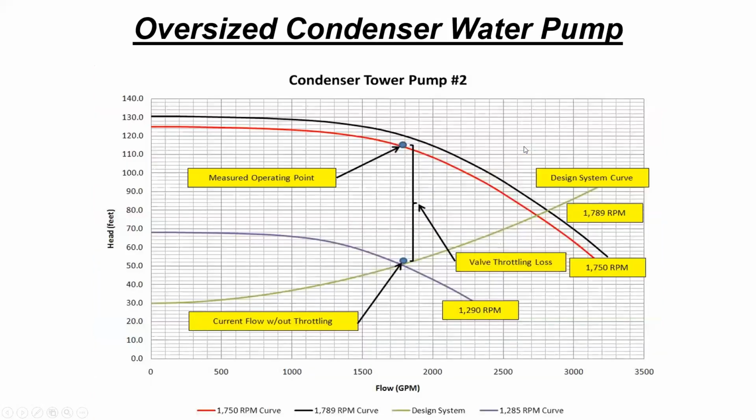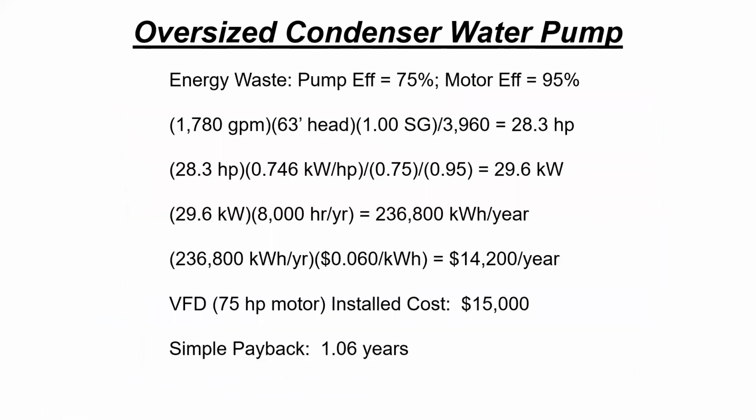So we're talking about going from here to providing this much flow rate, let's say 1700, by opening the valve, reducing the pressure drop by using a VFD and bringing the head down all the way to 50 from 130, let's say, or 120. Again, opening the throttle valve, but using a VFD to bring it down.